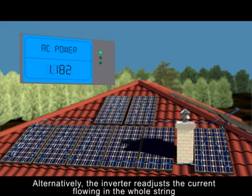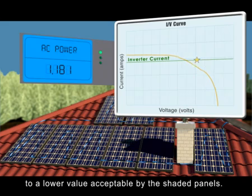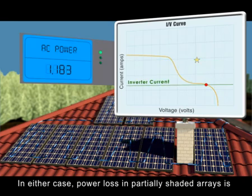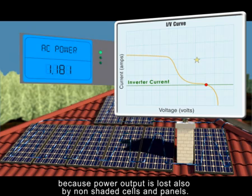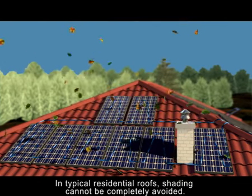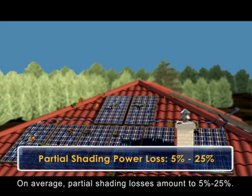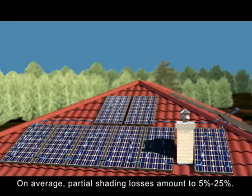Alternatively, the inverter readjusts the current flowing in the whole string to a lower value acceptable by the shaded panels. In either case, power loss in partially shaded arrays is significantly greater than the reduction in the illuminated area, because power output is lost also by non-shaded cells and panels. In typical residential roofs, shading cannot be completely avoided.